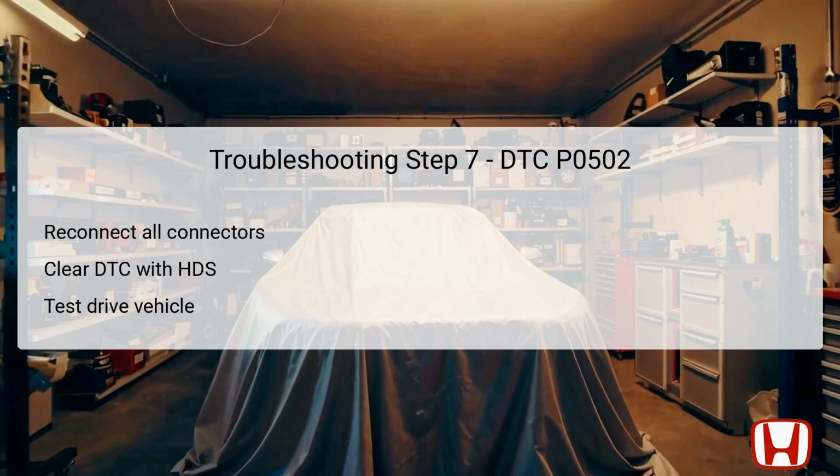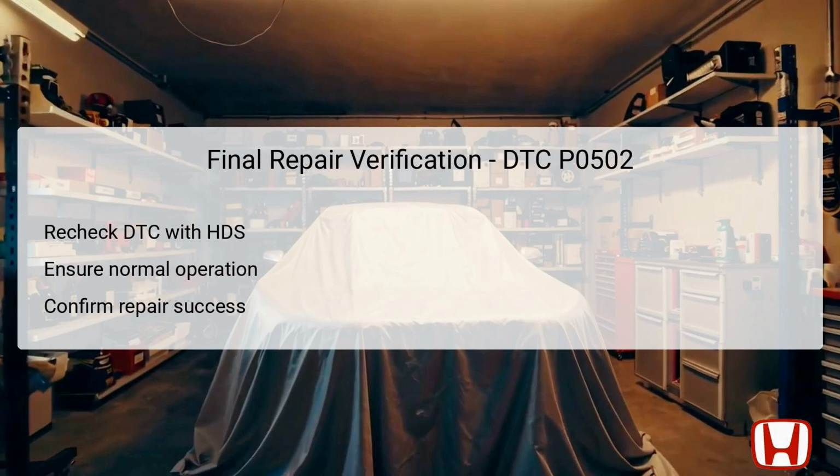Post-test drive, utilize the HDS to check if DTC P0502 reappears. If it shows yes, the CVT speed sensor likely needs replacement. Conversely, if the code does not return, then the sensor is operational and should be updated or modified accordingly based on previously mentioned steps. After completing all necessary repairs, it is vital to conduct a final repair verification using the HDS to ensure that the DTC P0502 has been successfully cleared.